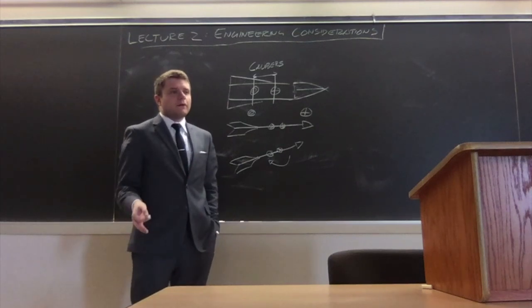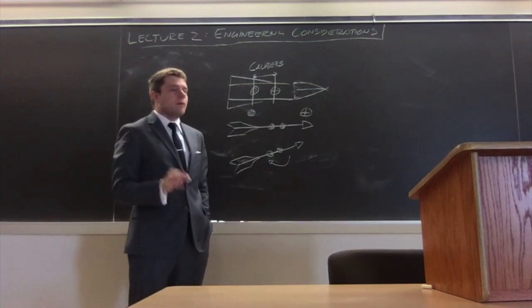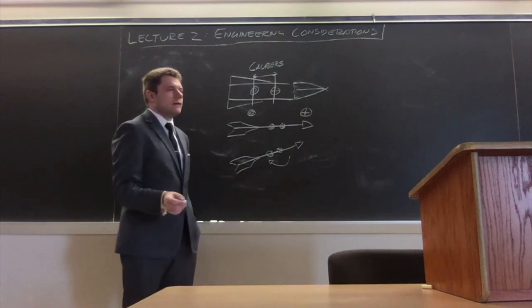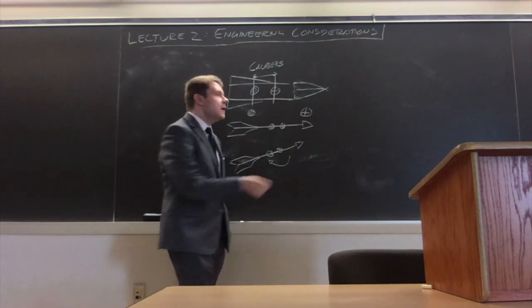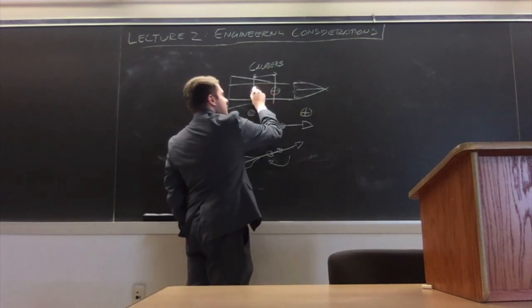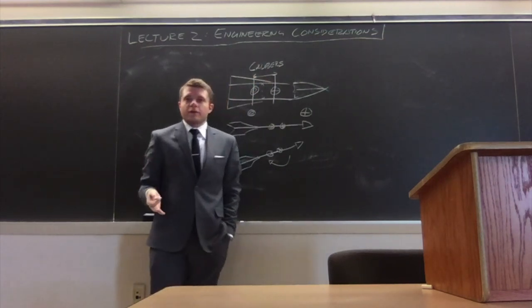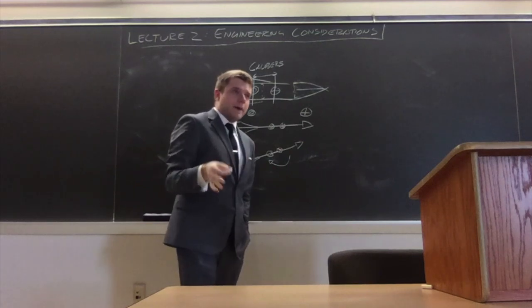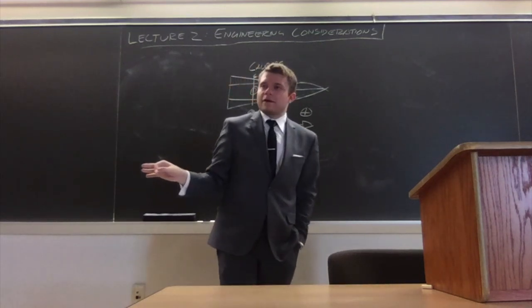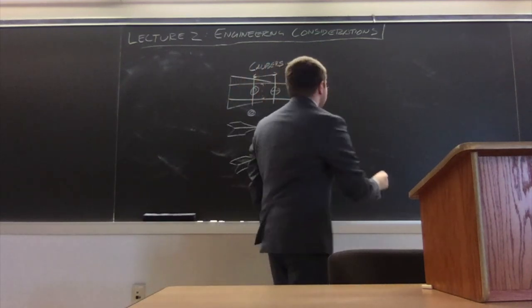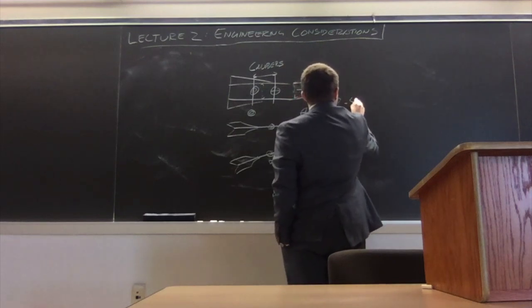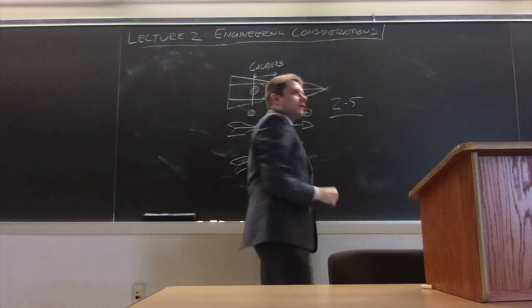Do I know why it's called this? I'm not entirely sure, and I won't pretend like I know because I didn't think to look that up on Wikipedia before today's lecture. But it's basically a function of how many diameters apart those two points are. And when you're designing a high-powered rocket that, again, has no active control system on board, you're generally shooting for between 2 to 5 calibers of stability.